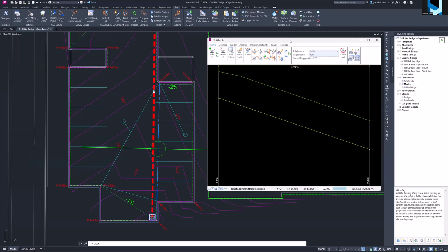And this is a touch point that I needed to make. It's important that if you assign something to the very start and the very end, as far as Cogo points go, what you'll find is that when you click on that Cogo point at the start, the chainage will have been nudged forward by 2 mil. That was to do with something happening with the lot grading, whereby if you had a loop, the software couldn't quite pick up the start and the end and assign it to one Cogo point. So we've nudged it forward.